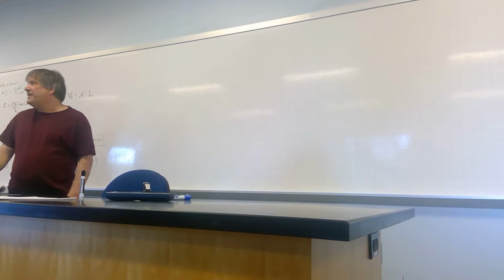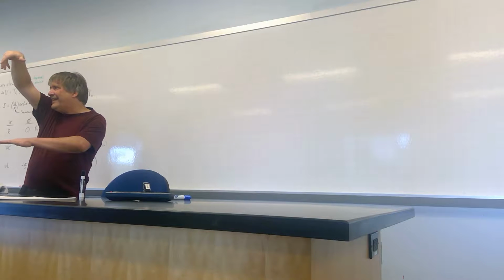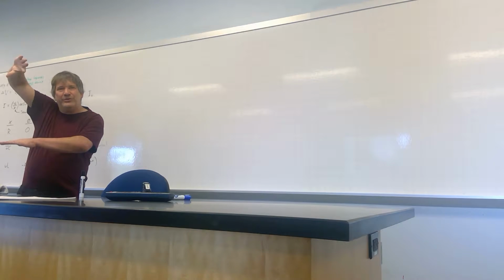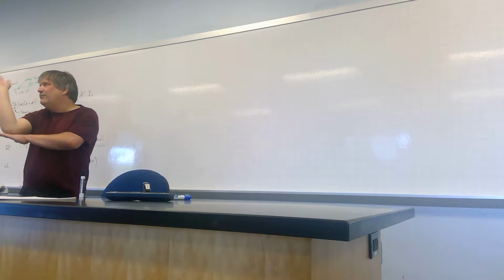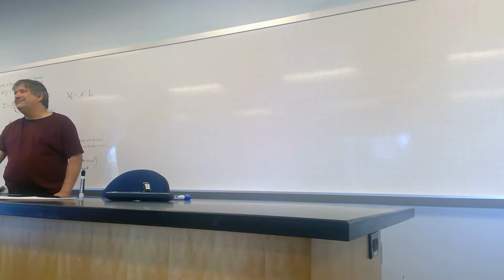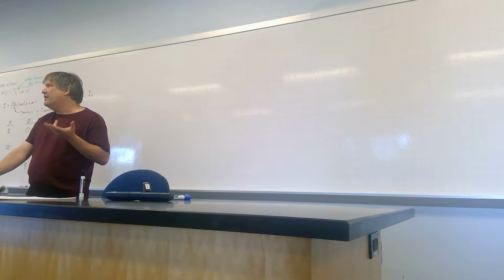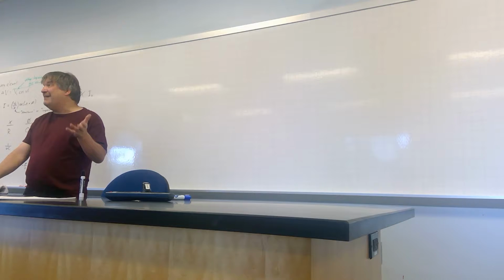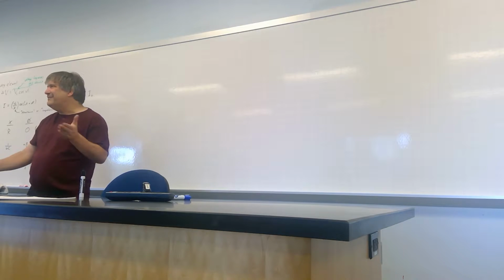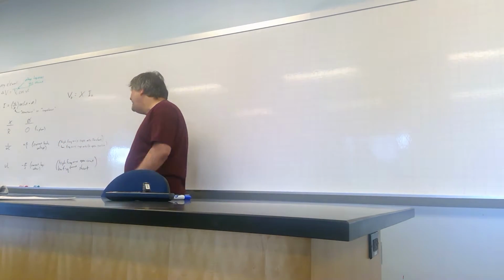By the way, the reason I say one of the natural frequencies is usually there's more than one way you could make a building oscillate. And a different Godzilla could come up and twist the building and let it go. And you'd have a natural frequency for that torsion mode. You'd have a natural frequency for it spinning, oscillating on this axis. You might have a completely different natural frequency for it oscillating on this axis. So an architect who's working in seismically active zones has to be aware of all those different modes of oscillation that their building can undergo and make damn sure that they don't match the probable frequencies of earthquakes in that region. All right, so that's the phenomenon of resonance.